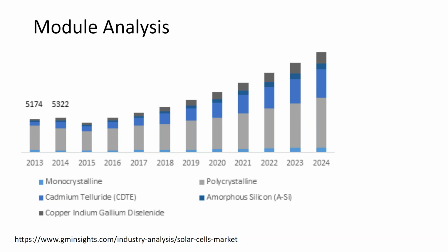Typically, the non-silicon panels are a little bit cheaper, but they're usually less efficient, less space efficient. So they take up a little bit more space. So it's a trade-off between efficiency and the other system costs. Some of the more experimental modules say, well, let's try and combine them together. Maybe we have a translucent thin film on top of a silicon panel, but those are still more in the experimental phase than in common use.